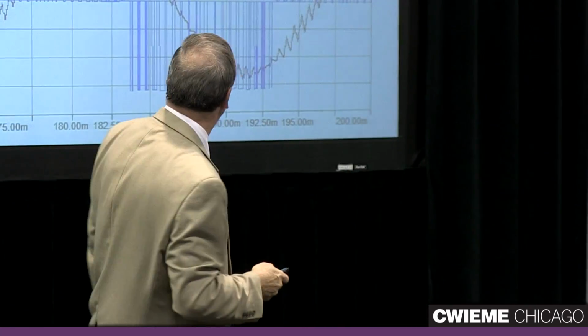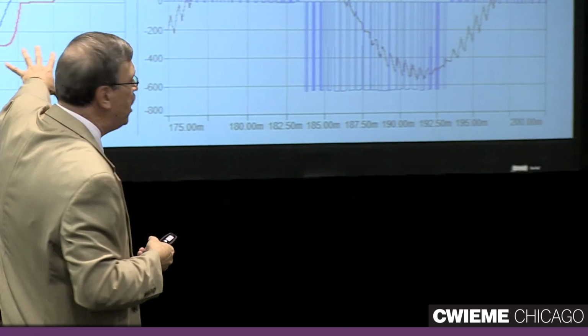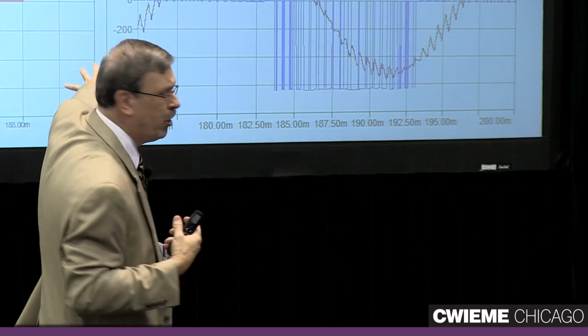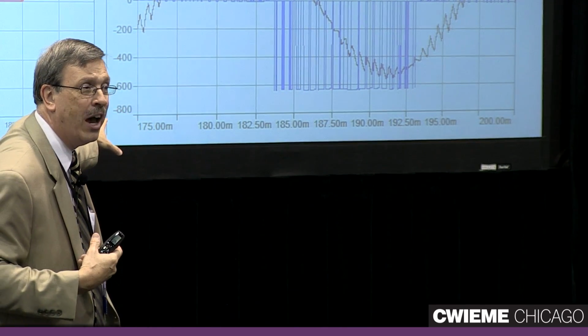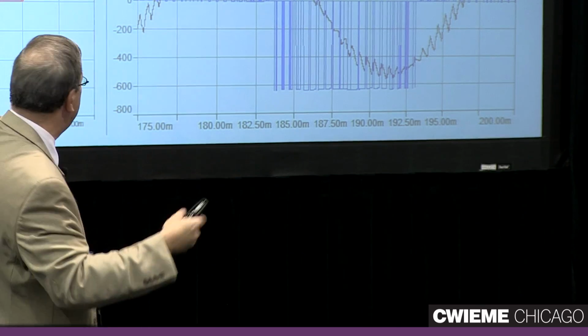But when you put a drive in there, things change. They change two ways. On the input side, what the transformer that's feeding the system sees, it's going to have to start providing pulses of current to that drive. And when it does that, the current no longer is going to look like a sine wave on the input side, and it contains harmonics. And we'll get into that some more.